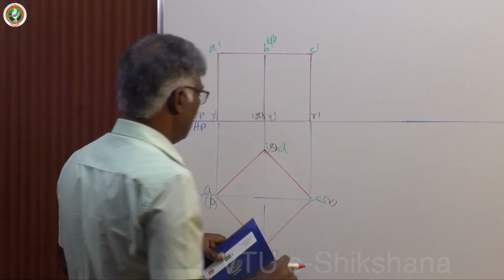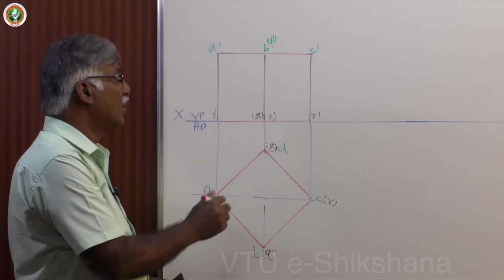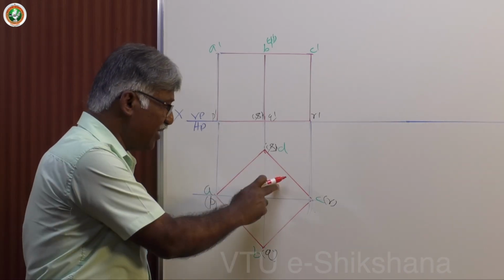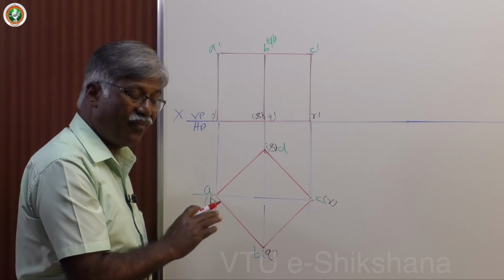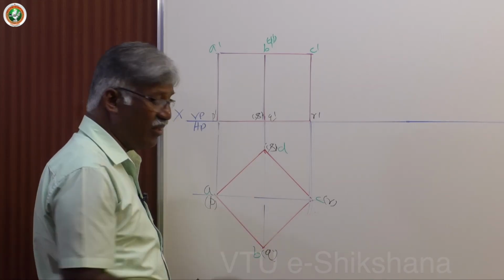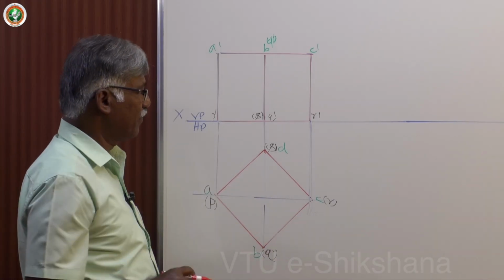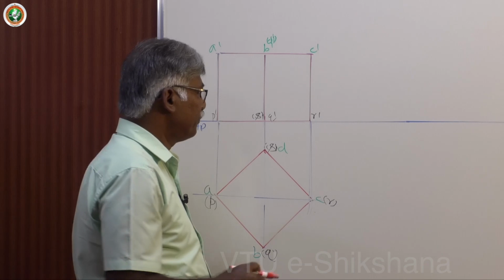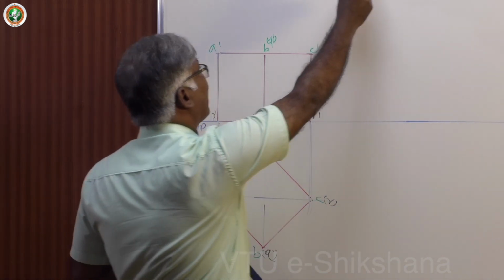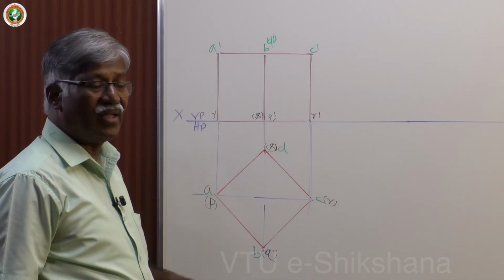This is front view of the cube, which is placed with simple position. I can say all sides are equally inclined to VP, or one of the sides is inclined at 45 degree to VP, or corner condition, simply corner condition for all even number of sides with one diagonal parallel to VP. Okay, that's all. Next, I have to keep this R on ground. Not necessarily, if rests on HP is not given, I could have taken little up and I can keep it in space, no problem.